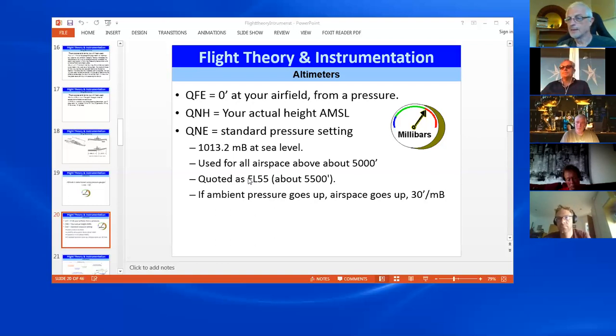So do bear that in mind if you approach airspace and leave a big enough margin. We normally say don't get within 500 or 600 feet of airspace, so that you've got a margin of error to avoid getting into it. So you don't try and scrape it, going, well, I just got up to 5,499 and missed it by 12 inches. Bad idea. Really bad idea. Aircraft are big, you're small, you don't stand a chance. So it's not exactly flight theory, but it's worth pointing out.